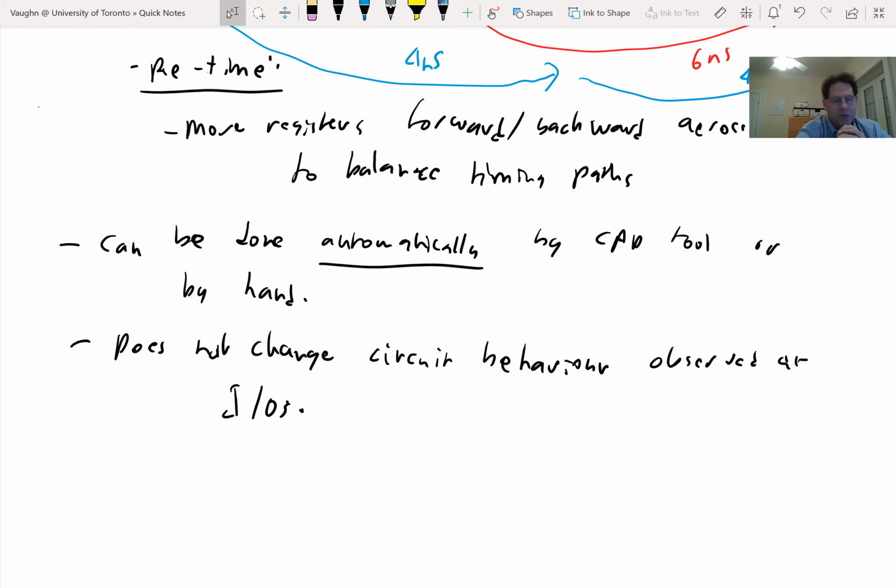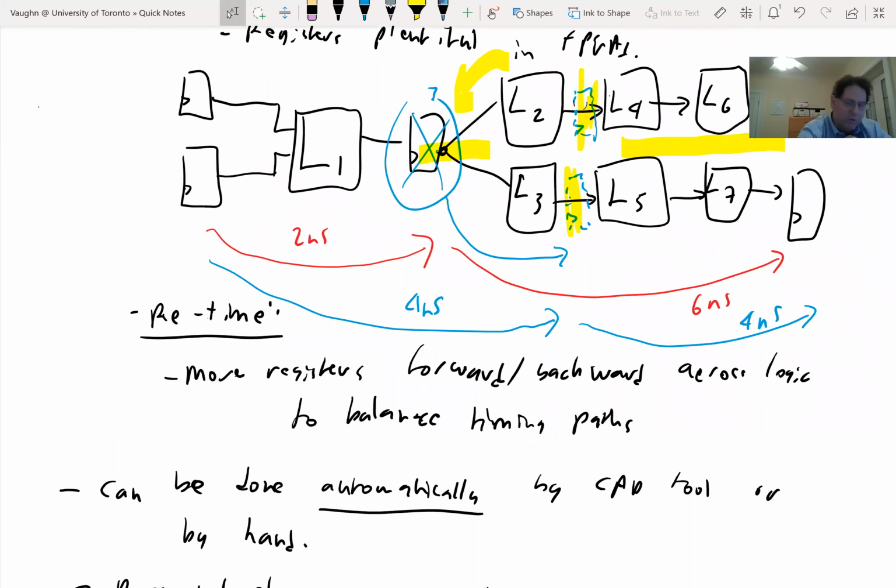But the key reason they don't turn it on by default was harder to debug. So if you actually bring up a retimed circuit in a simulator, you don't know what the registers are. So in your HDL, you wrote, this is an enable register, and this register represents this state, and this register is the sum of the following 3 values, and so on. You gave your registers hopefully very good names, and you understand what they do. After they've been retimed, they've been moved around, you don't actually know what those registers are doing exactly. They're hard to give names or describe their functionality.